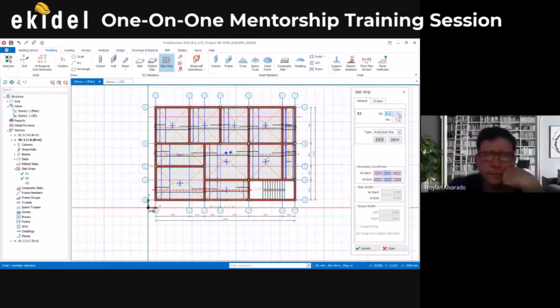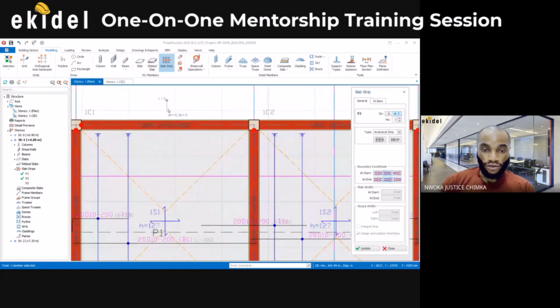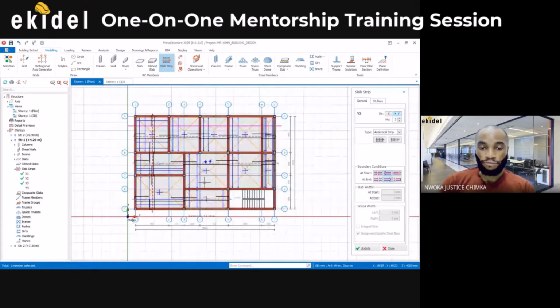I'll then change to Y direction. Again, the Y direction is still beam to beam, so I will still be on that beam to beam, and I'll cut again from here to here. Okay, I have that now. Again, I'll move to the next panel.